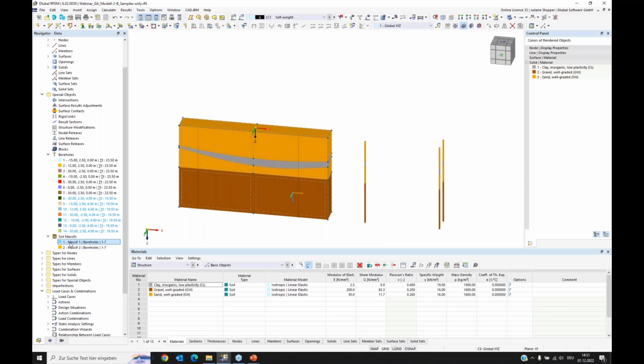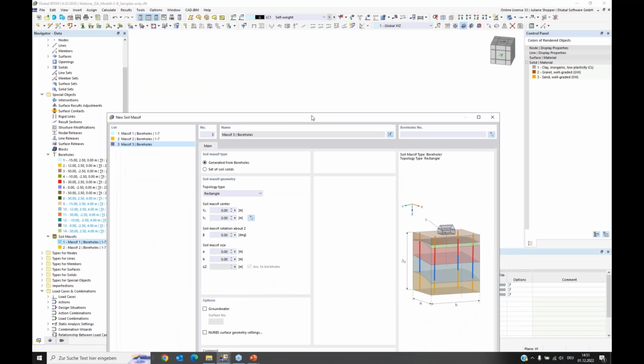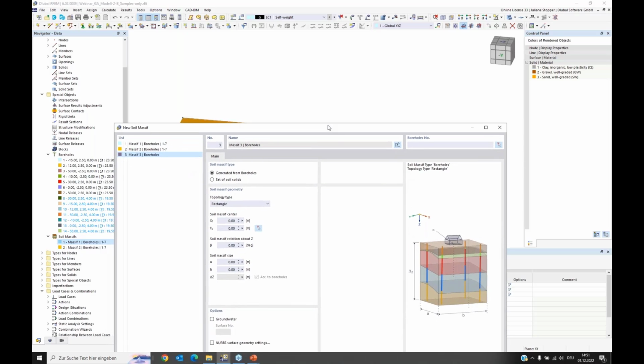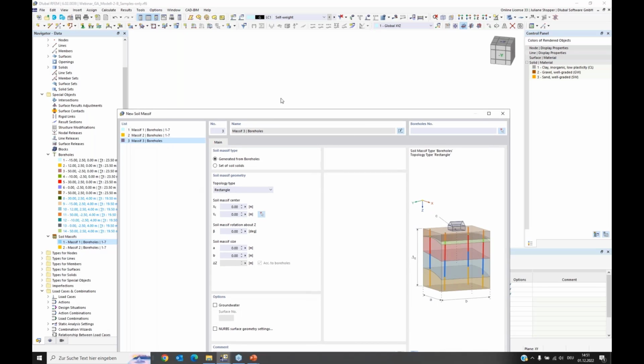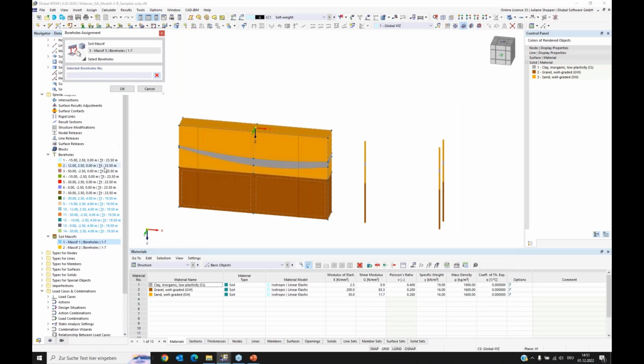Okay, what I can do else is I can define a new massif, and I want it to be placed in a deeper depth. I mean, I want the surface to be in a deeper depth. So I will do it like this. I will use a copy. I copy this massif, and it will be placed at 30 next to the previous one, and I will use other boreholes. For this case, I prepared a copy of these boreholes, and in that copy I set another Z value, and the height is different. So you will see the effect soon.